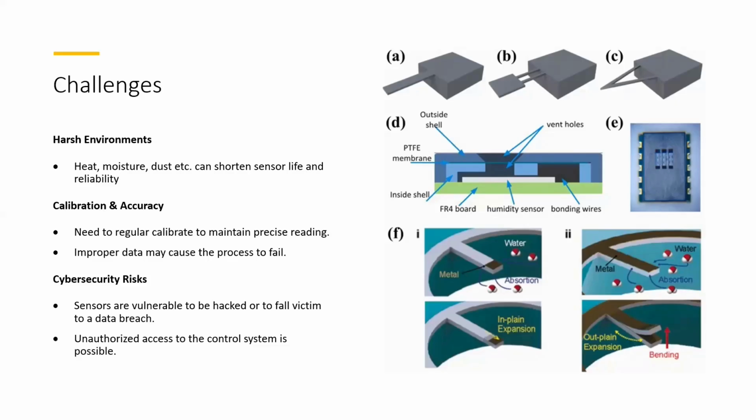And secondly, another challenge: calibration and accuracy. There is always a need for every one of these sensors, like the pressure sensor I mentioned before, to be calibrated. Usually it is a job done by the technician. Usually it is a zero and span calibration, or what I can call maximum and minimum calibration, to help the sensor know its own accuracy perfectly and carry out its measurement perfectly.